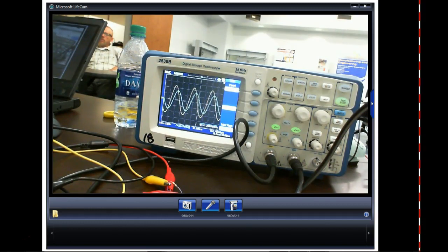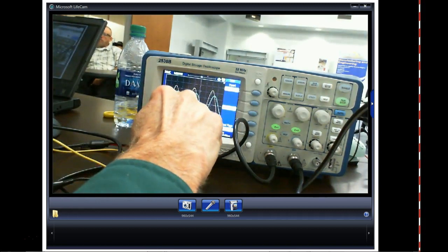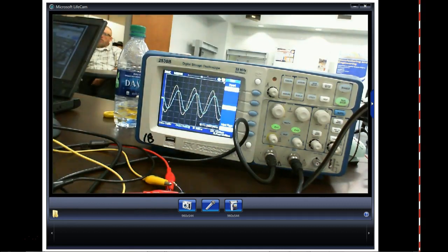If we didn't have a phase shift, there would be no such thing as a single phase motor. Because to cause that rotor to turn, your magnetic field has to shift. So inside of single phase motors, we have a special winding called a start winding in which we deliberately create a phase shift. So when this one starts down, this one is coming up, and it causes the magnetic field to shift, and what does the rotor in the motor do? It turns. So we have what we call capacitive start motors, and that's what they are. Now once the motor's in motion, it creates the phase shift itself.